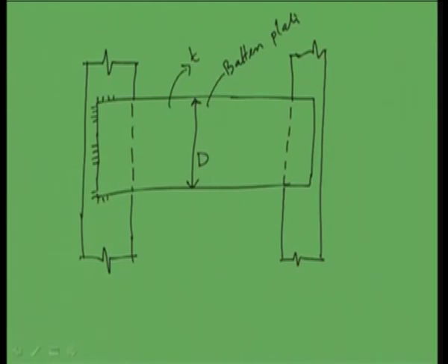First we have to decide what is the total length required for welding with a particular thickness of the weld. Then we have to distribute it properly, so that the codal provisions are maintained as well as the total lengths are also maintained. So, if I say A, this should not be less than d/6, where d is the overall depth.